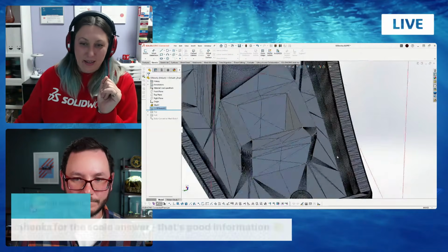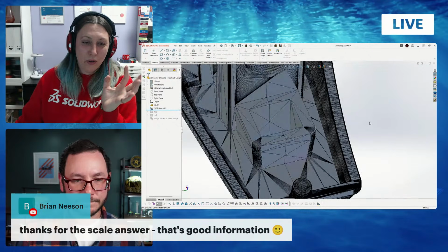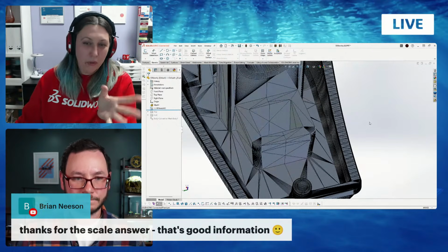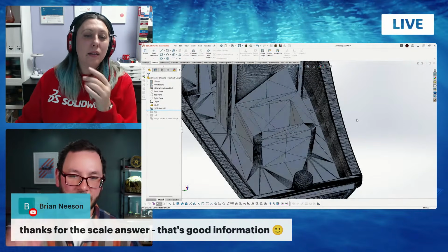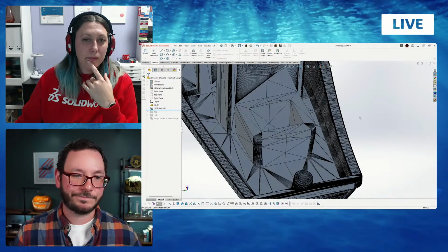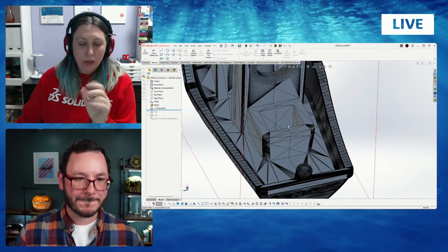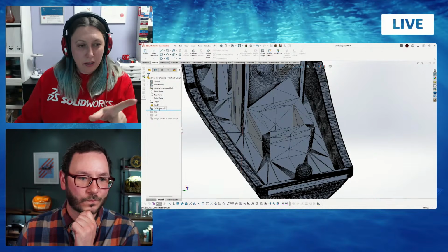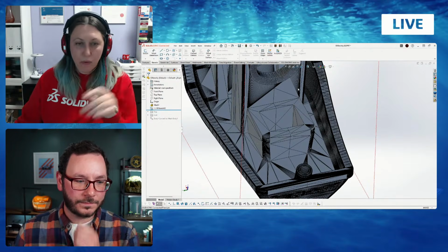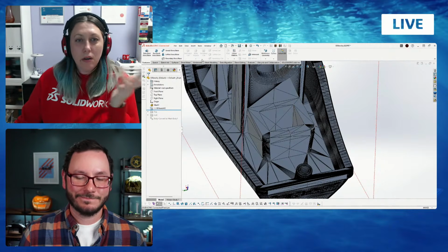And we exit the 3D sketch. Why do we go to 3D sketch? Because only 3D sketch can snap to any point we want. Yep. You can put all that information in one place without having to deal with all those planes, right? And yeah, so I will show just the first steps. I started with converting this one. And then later I will just show the top hull, the whole feature tree, because there is no point to convert everything.